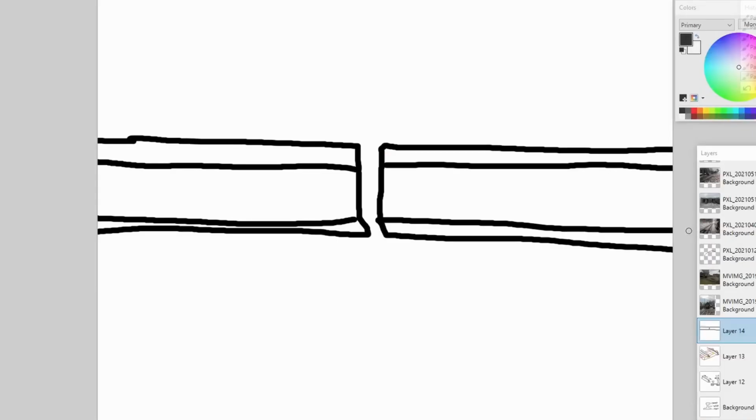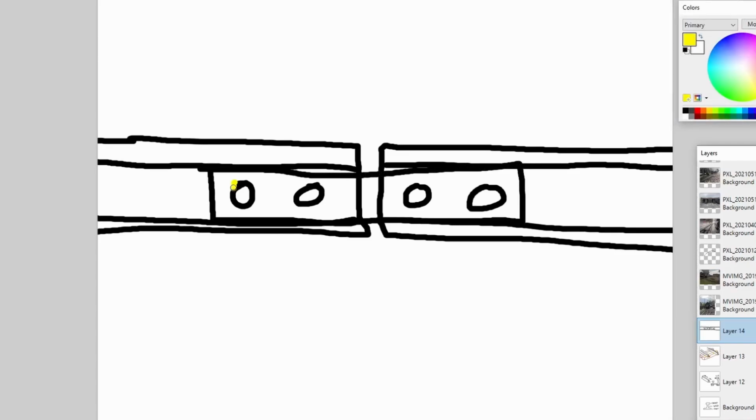The next important thing to talk about is how we actually fit the different pieces of rail together. So we have two rails here on the left and right, and typically the early way to do it was to use what is called a joint bar. So you would drill 2 holes, 3 holes depending, in the web of the rail, and then you'd apply a nice flat piece of plate, and then you'd stick some bolts in with some nuts, and I'm using square bolts because, you know, olden day railroad stuff. But this is the earliest way to set things up.